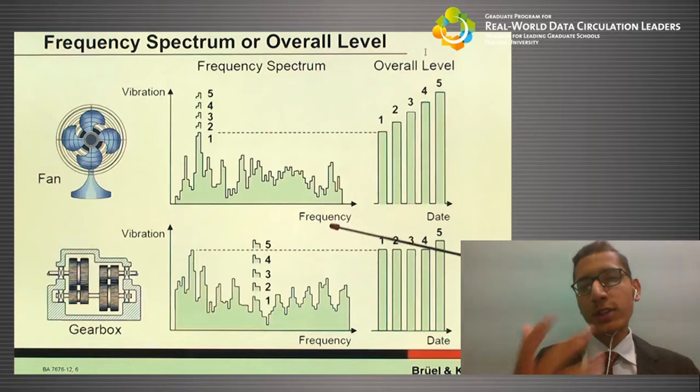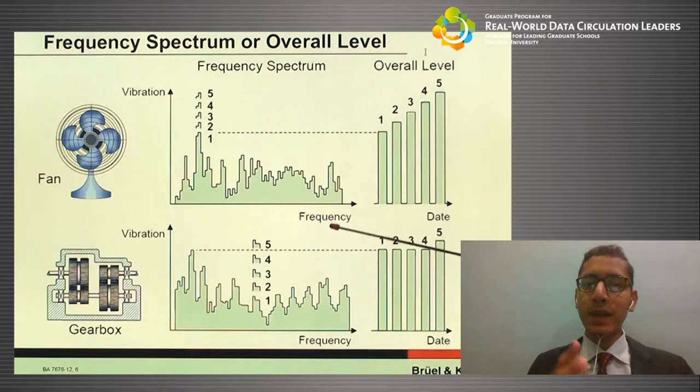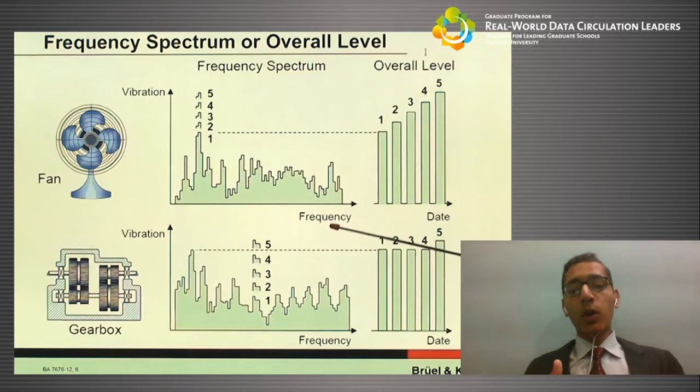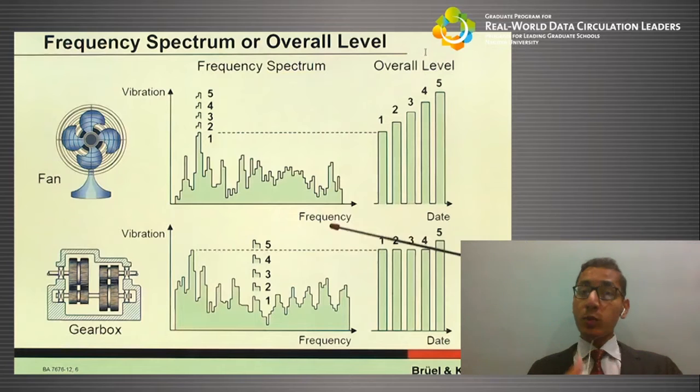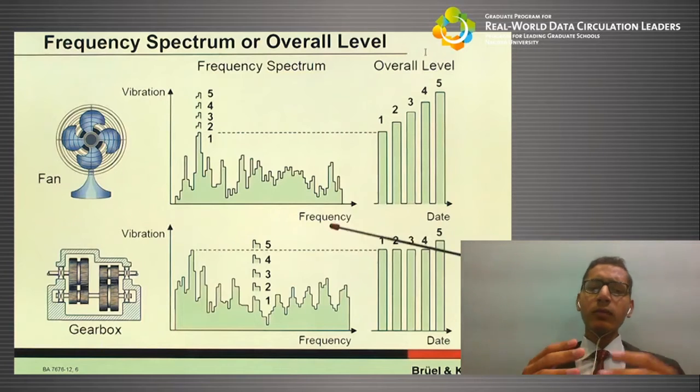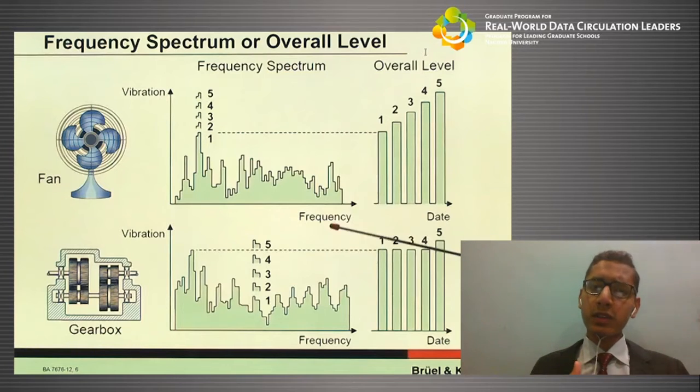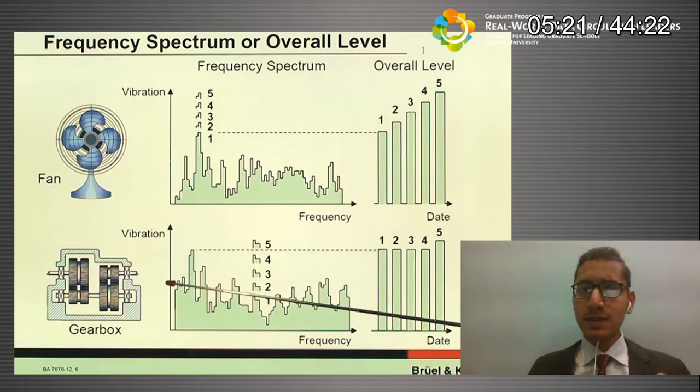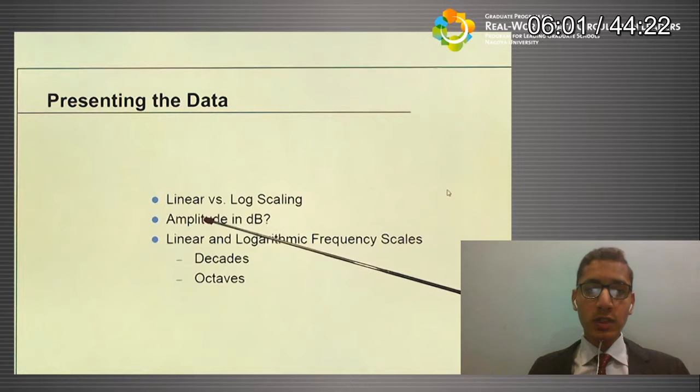So as the vibration is increasing, we know that this part is unbalanced. So we need to either remove it or we need to see how it can be balanced, how we can smooth out its frequency. Now, as it is relatively increasing, we know that this part is damaged. So we need to focus on this, and then we need to change it.